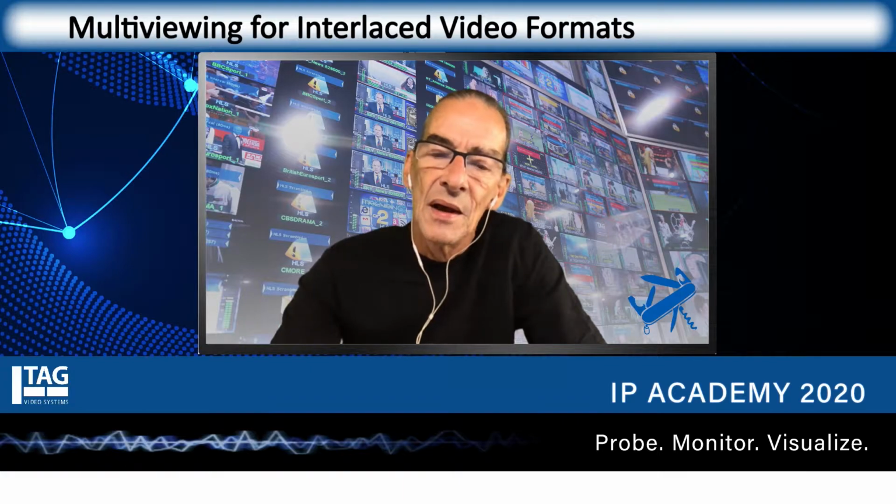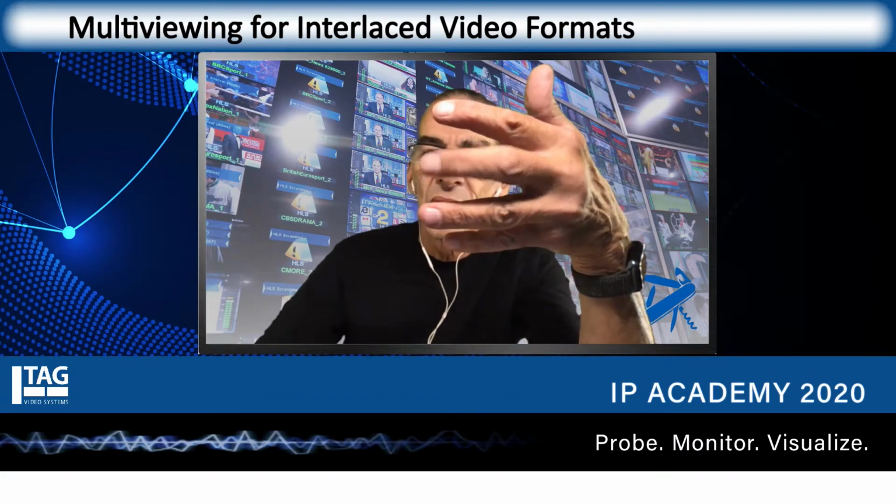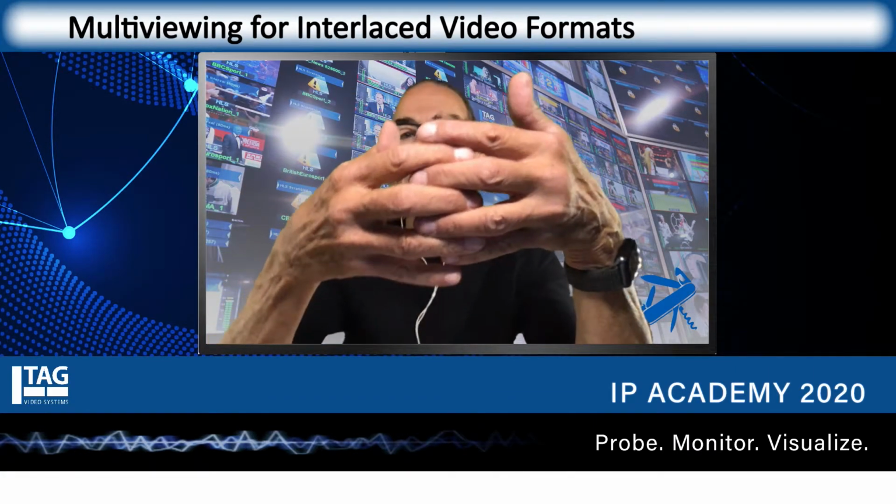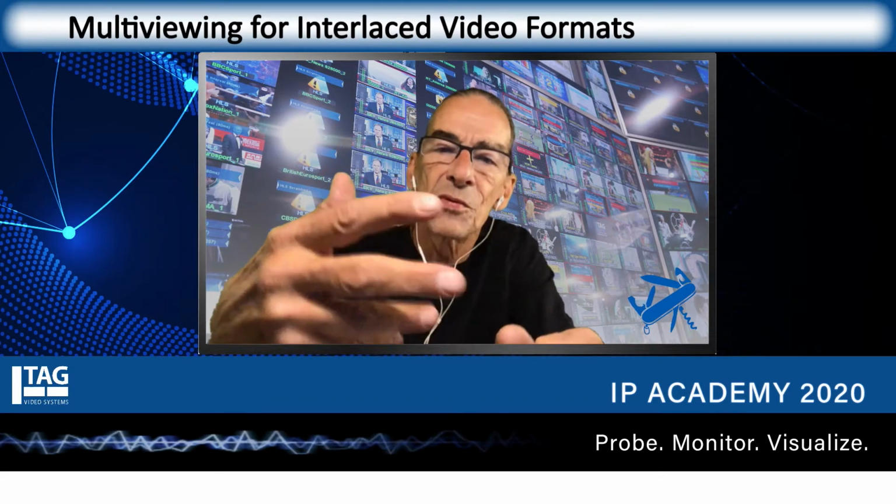And so actually, an inventor named Theremin, who's better known for his musical instrument of the same name, came up with this scheme called interlacing, where the picture was actually scanned twice. The reason for scanning it twice was to reduce the bandwidth, and the way the bandwidth was reduced was by scanning one half of the picture each time. The trick involved here was that it was reducing the vertical resolution by scanning first the even lines and then scanning the odd lines in the picture. So lines 1, 3, and 5 would be scanned first time around,